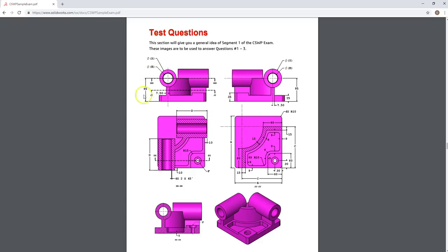So they've cut the top off primarily to show you the D dimension here and here, and they've put in this fillet here because it was too crowded in other places. The JJ through JJ cutting plane line goes lower, and it removes the entire top half, because what they want to show you in JJ through JJ is this rib looking feature here. And so they just went ahead and they came up a little bit and cut it off and removed all this. And so that's what you can see there.